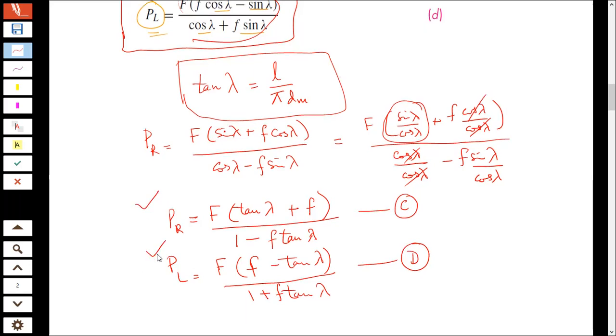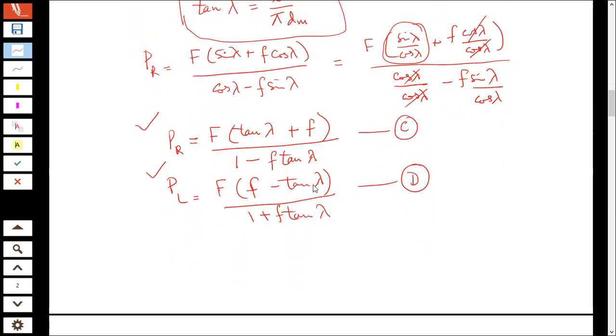Now, what is torque equal to? Generally, when we apply force on the screw jack, we multiply that with the radius. The product of force times the radius, or the force arm, is going to be the torque required to rise the load. So I'll just put r, the radius, but this is going to be the mean radius.